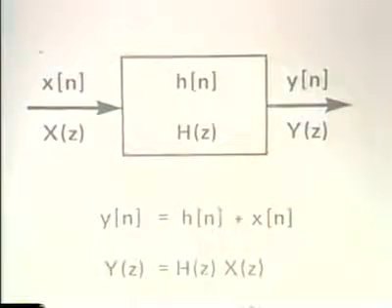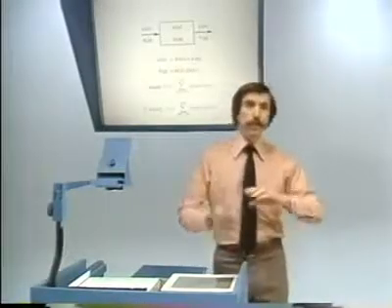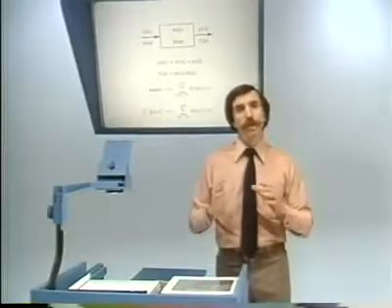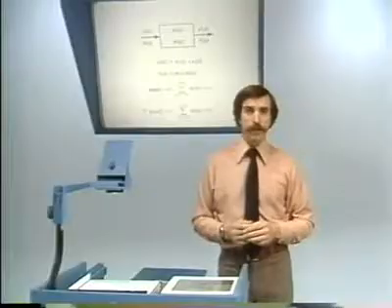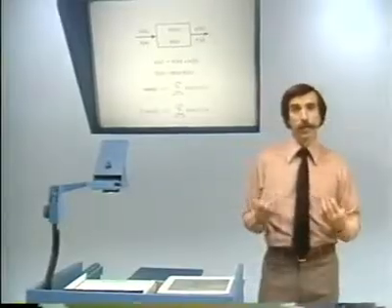Again, very much the same as what we had in continuous time and also what we had in the context of the discussion with the Fourier transform. In fact, because of the relationship between the Z-transform and the Fourier transform, the Z-transform of the impulse response evaluated on the unit circle, in other words, for the magnitude of z equal to 1, corresponds to the frequency response of the system. More generally, when we talk about the Z-transform of the impulse response, we will refer to it as the system function associated with the system.